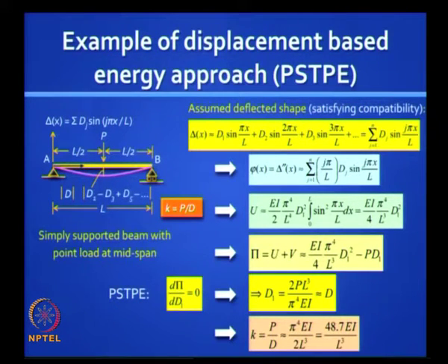and if you take one term, for example, and assume that the higher order terms are not important, you invoke this principle, you actually get an expression for deflection and thereby for stiffness which is quite close to the exact expression. What is the exact expression?